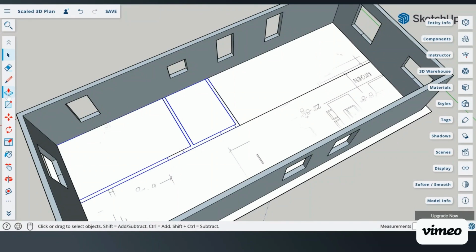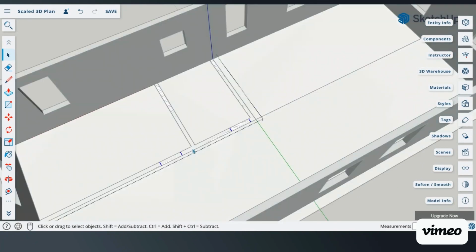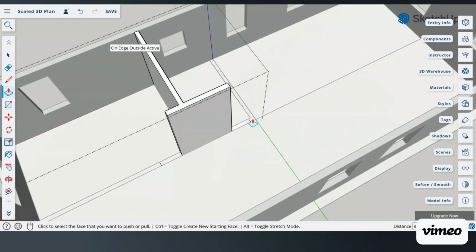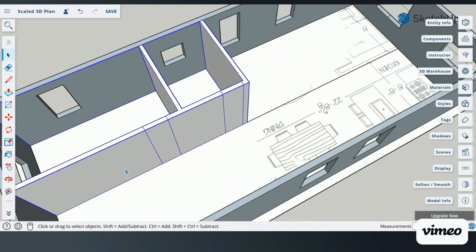While I'm in this group, I can go ahead and use that push pull and bring them up. But you need to use your arrow, double click or triple click inside so that you now are inside of your interior walls, and use your push pull and pull your walls up to the 8 feet. I'm going to skip my openings for a second here, and then go through and pull these openings up. So now we have our interior walls pulled up, at least on one side, and they are all one group.